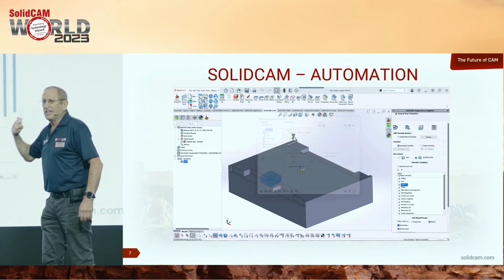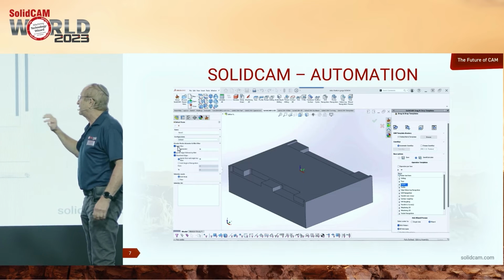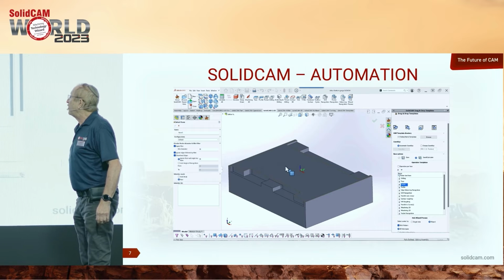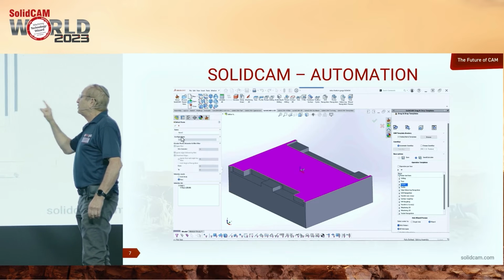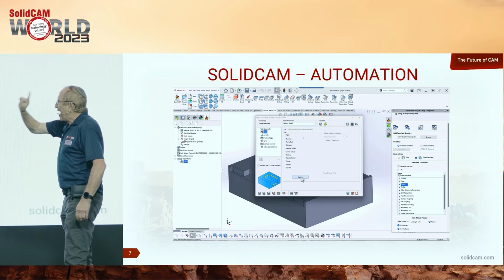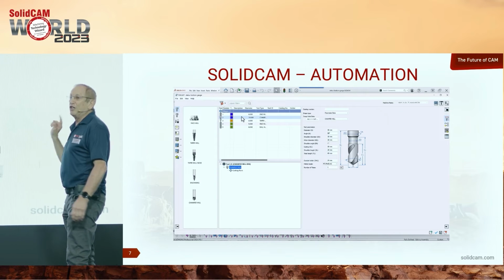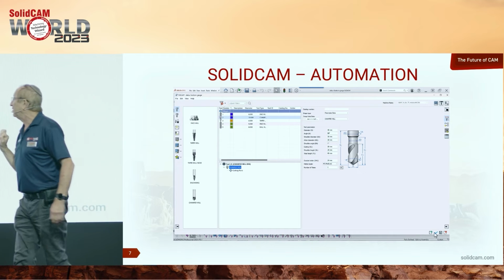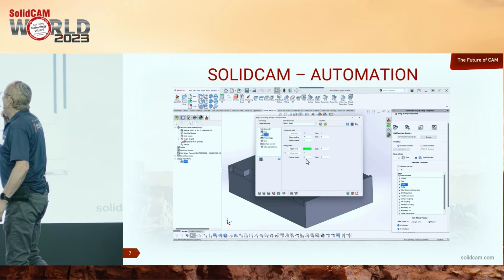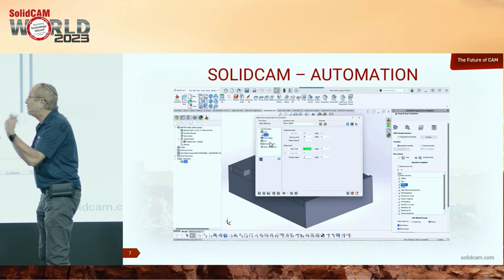Now, let's create a geometry. In this particular case, I just want to create my geometry using the top face. So I'll choose the option of just one face, and I'll click on that face. Now, note also that little boss. What about that boss? That boss is going to cause us a problem, isn't it? That's right. It may in most cases, but let's see what actually happens. I'm going to use a 10mm chamfer mill. And what I'm also going to do is give it a chamfer depth of 0.5 millimeters so we can actually see what's going on.